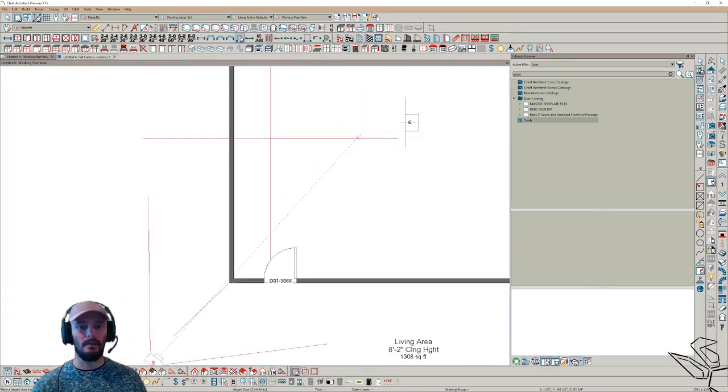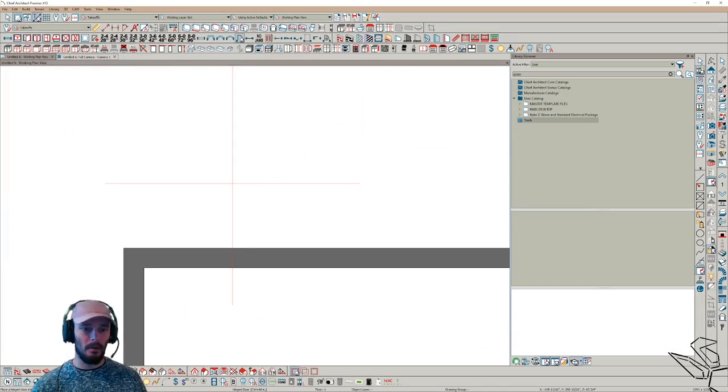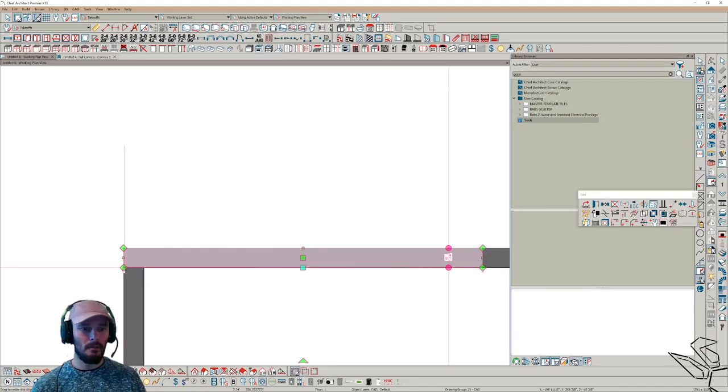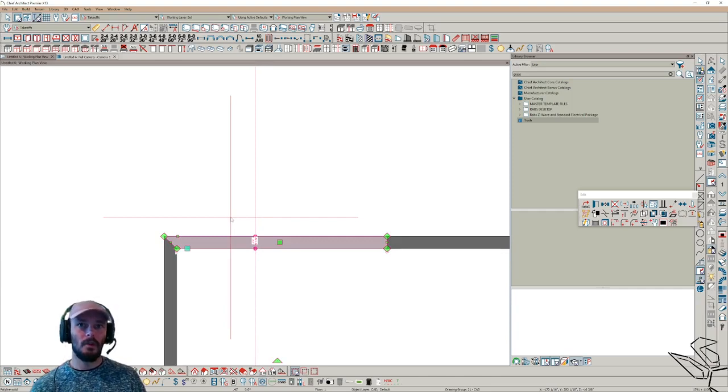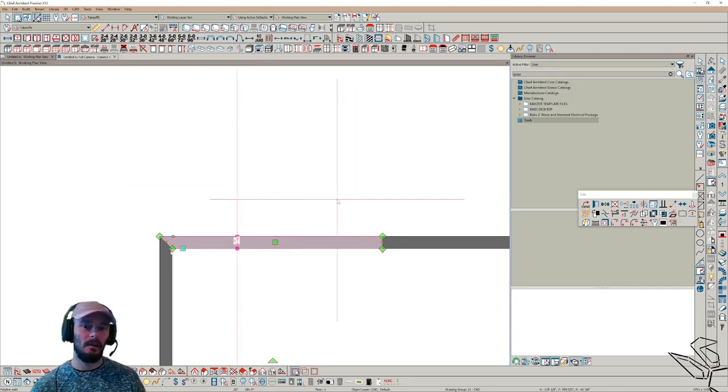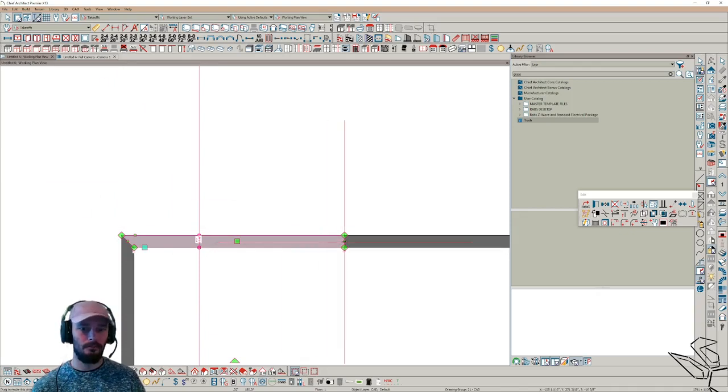Well, we can create a frame as a fixture to cut into our wall. And that's what I want to do. So I'm going to go over to this opposing wall right here and just draw out a couple P-solids. Okay, I'm going to snap it to the wall itself. I'm going to make it just a one-side piece so that when we're utilizing this as a tool, we're going to have to copy it and reflect about the corner.